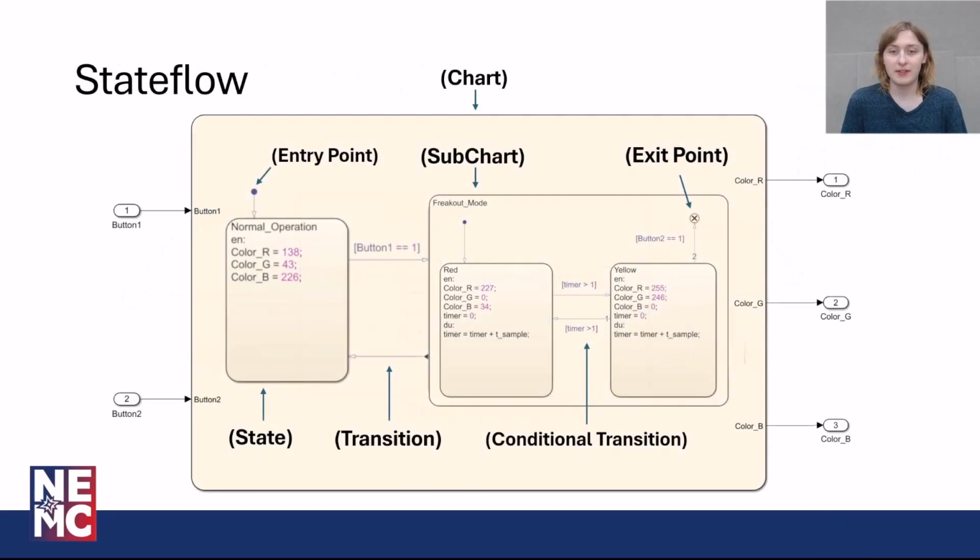Simulink also has another tool inside of it as well. It's called Stateflow. Stateflow is a block coding state machine tool. These state machines are encapsulated in charts, which, as you can see on the edge of the screen, interact with Simulink as well. We usually have at least two of these. The first one is for the autonomous routine. The second one is usually some sort of chart that tracks the position of the game piece in the robot and how to move that game piece.